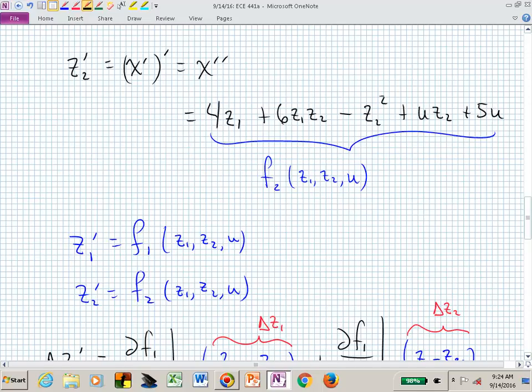And one such condition would be to just set Z1 to 0 and U1 to 0, and then we have everything being 0. Just like the equilibrium being down, we have the angle is 0 and the velocity is 0. And we're linearizing about that position.